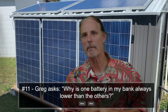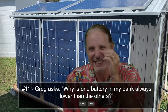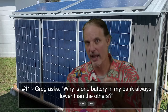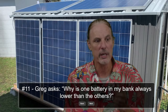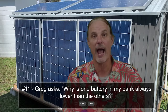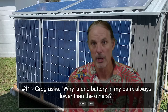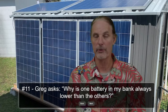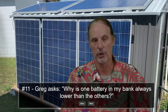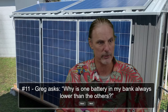So this is what's important for you to understand: there is no exact science here. It's about getting as close as we can and calibrating the best we can, but you're going to have some that are lower than others. So you may have to calibrate certain batteries to get them more accurate so that they fall closer in line with the other ones. But the best solution that I've come up with so far is to go to a universal calculator like a Victron shunt or something, where you're calculating the whole pool of batteries and not just individual batteries.